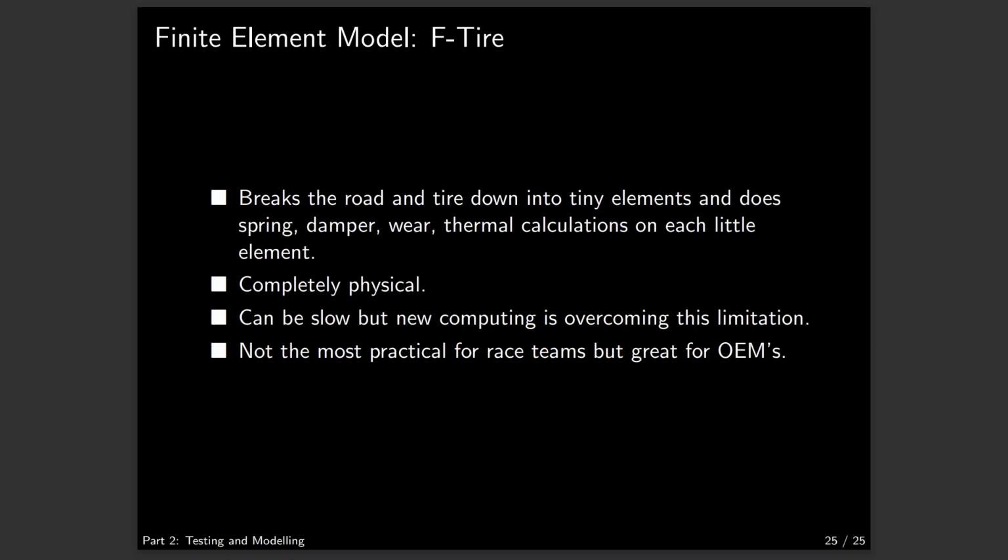Finally, we have F-Tire. This is a finite element method where we break the tire down into several tiny elements and apply stiffness characteristics to each element in the mesh. This is the most advanced way of modeling your tire, but is computationally demanding and not recommended for student teams.